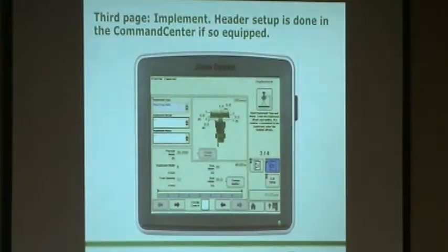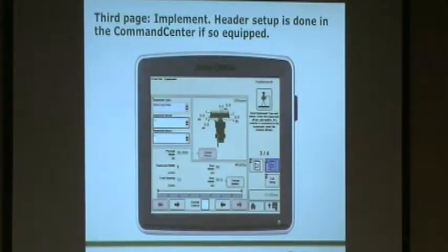And then if you click on your next page, it'll bring you to your equipment, your implement. Okay, so row crop head, implement model, implement name, you have to enter that stuff in. But if you notice down here, you have a physical width of 30 feet. Well, once again, it all depends on whether you have an 8-row head or 12-row head. Here we have implement width is 8 rows, so that's not going to be 30 feet if you have a 30-inch corn head. So you have to change that to 20 feet. Your track spacing needs to be changed to 8 rows on 30 inches.